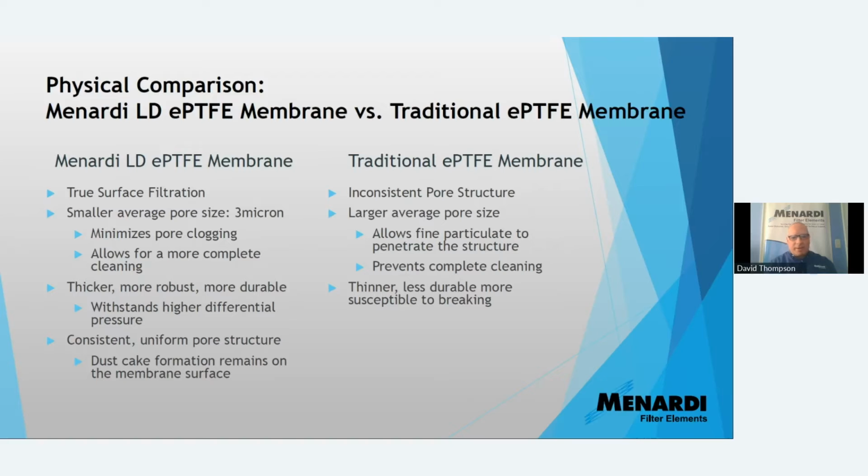It's a thicker, more robust membrane, so it can take the higher differential pressure, and it can pulse under standard, up to 90 pounds, 110 pounds of compressed air to clean them. It's a very consistent pore structure that makes it very easy to clean repeatedly, versus the old type of membrane,